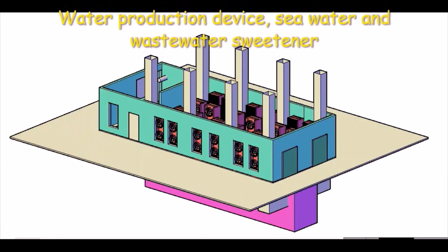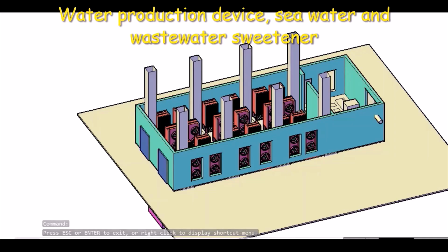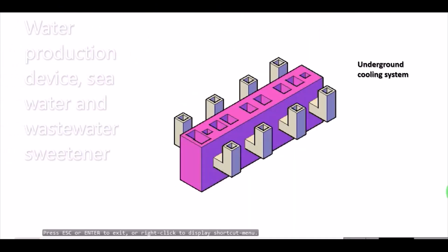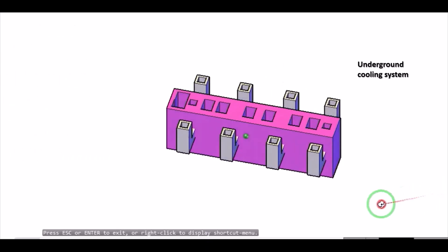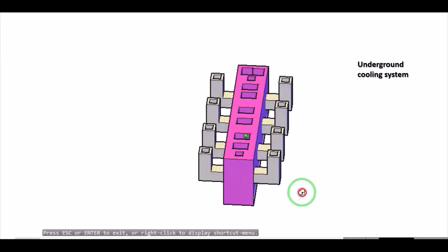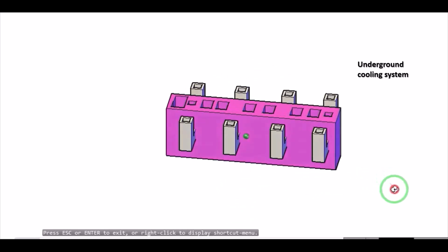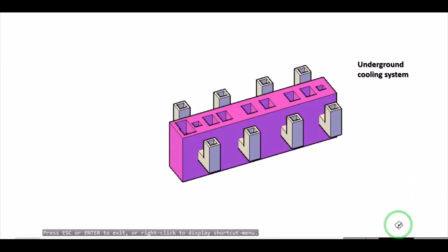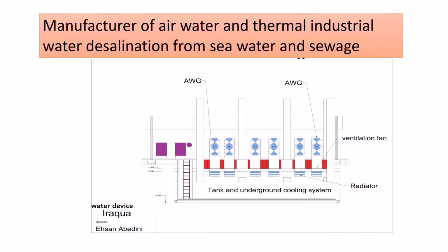Refrigerant density atmospheric water generator, AWG, is a refrigeration condensing system that produces water from the atmosphere. A compressor circulates the refrigerant through a condenser and delivers it to an evaporator coil that cools the surrounding air. This process lowers the temperature of the air to the dew point and causes the water to condense. A controlled fan directs the filtered air towards the coil.